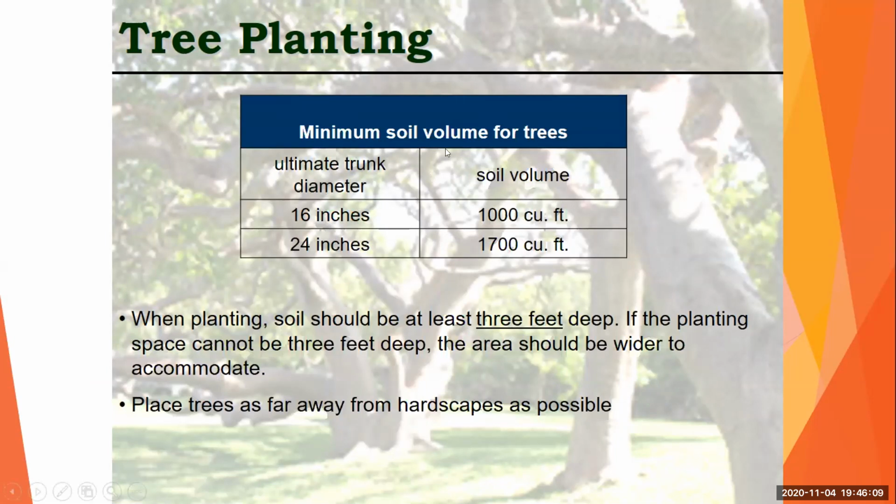People don't take this into consideration, but if you were going to plant a big tree, a 16 inch live oak, you need to provide that live oak with 1,000 cubic feet of soil, more or less. Otherwise you're going to have bonsai. So soil volume is also very, very important.